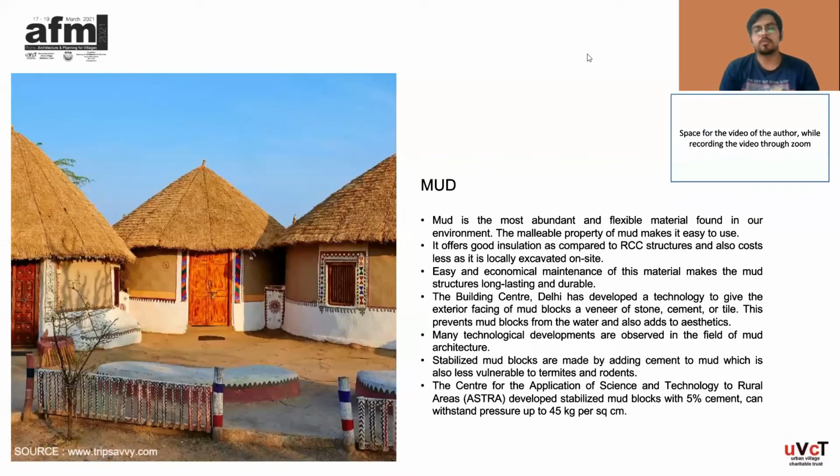Mud. Mud is the most abundant and flexible material found in our environment. The malleable property of mud makes it easy to use. It offers good insulation as compared to RCC structures, and also costs less as it is locally excavated on site. Easy and economical maintenance of this material makes the mud structure long-lasting and durable. The Building Center, Delhi, has developed a technology to give the exterior facing of mud blocks a veneer of stone, cement, or tile. This prevents mud blocks from the water and also adds to the aesthetics.